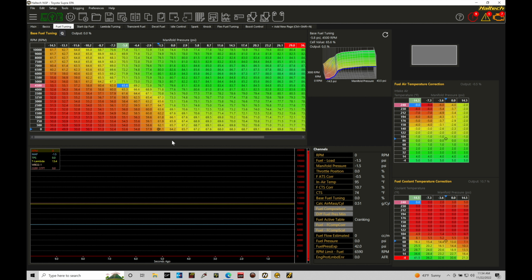It's actually really straightforward and a very powerful way that we can account for fuel pressure variations in our fuel system, which definitely happens. At least 75 to 80% of the cars I work with have some type of a fuel pressure problem, and that sometimes doesn't present itself until very high power levels. Sometimes it happens at lower power levels, but either way, it is something that we definitely have as a variable that can and will affect our airflow and fuel model. So regardless if we're putting in correct injector data or airflow is spot on, we can still have discrepancies, and it usually comes from fuel pressure. So we definitely want to integrate this.